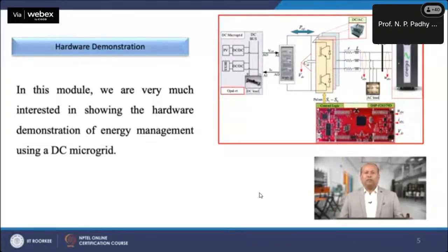The same current signal is either fed or drawn through a current source at the DC bus of the DC microgrid inside the RT lab of the Opal RT. This looping system between Opal RT and the power amplifier effectively emulates the DC bus of the DC microgrid.